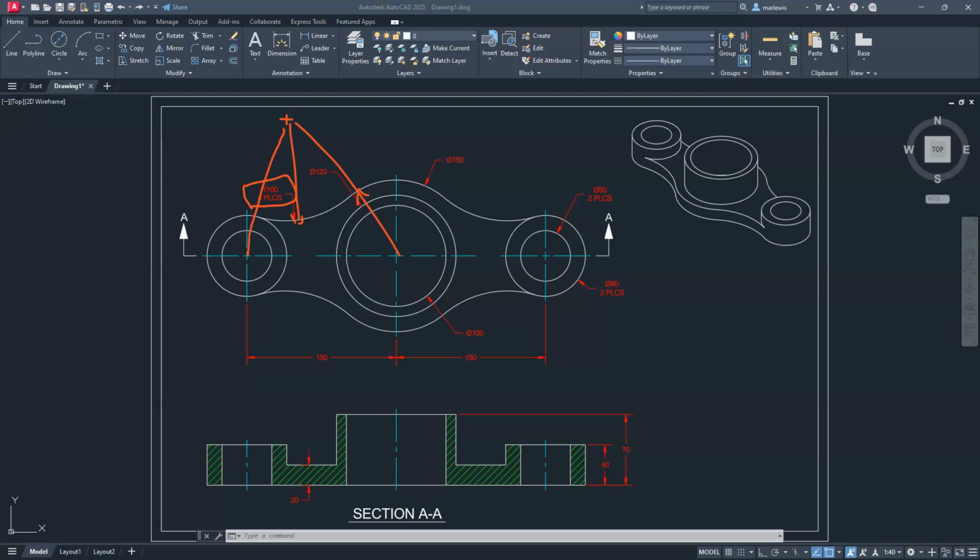You'll notice that the radius here is given to me as 150, so we're going to go half of 150, which is 75. If we add 75 to the radius here and make that distance 175, that's going to give me that whole entire length that I'm going to need for this circle. So when I get to creating this isometric, you're going to see me draw one circle at 175.